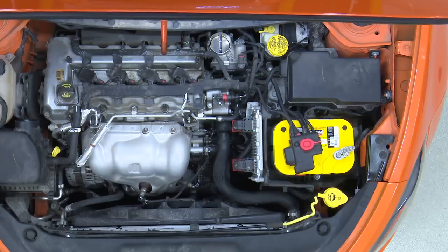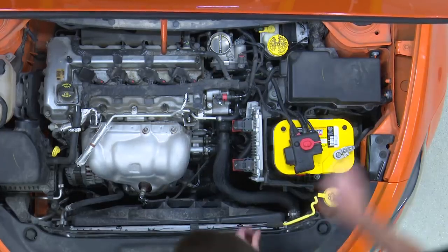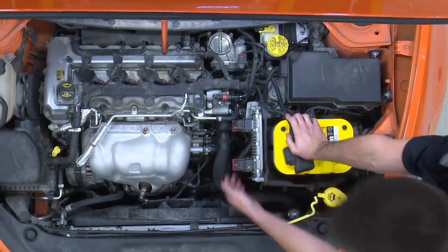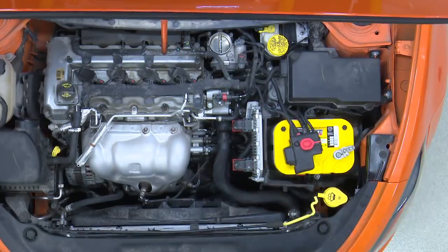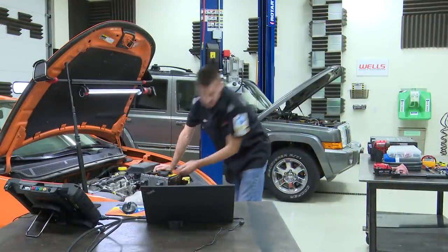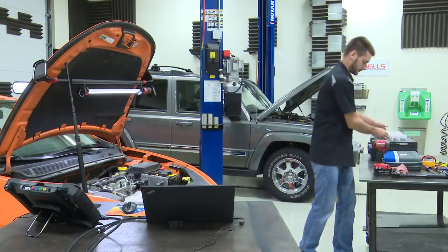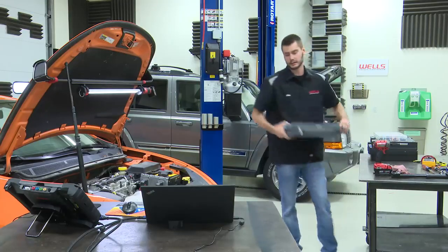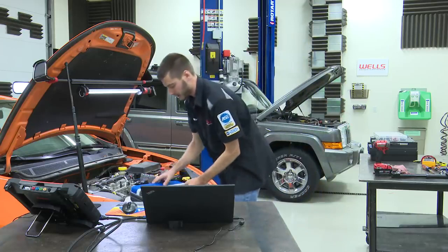All right, so I know it's going to be hard for you guys to see. We'll get to it in a little bit. But right down here, get my head out of the way, right down here is our transmission range sensor. So Jim, can you go ahead and turn the key off? What I'm going to do is I'm just going to start by grabbing some leads, and let's see what this looks like with it being ohmed out.